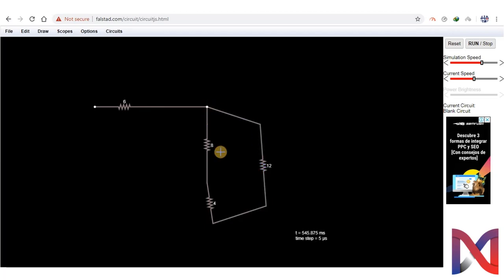Here we have connected the whole circuit. Now we will place another wire here so that we may connect our power supply here. As it is already clear that we need to verify Ohm's law for the R equivalent of the circuit, we first connect our ohm meter at this place so that we are able to know the R equivalent of the circuit.